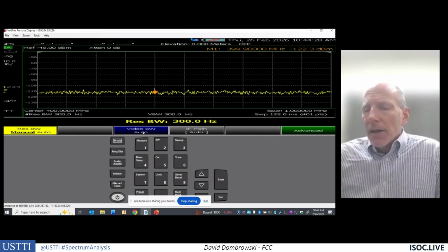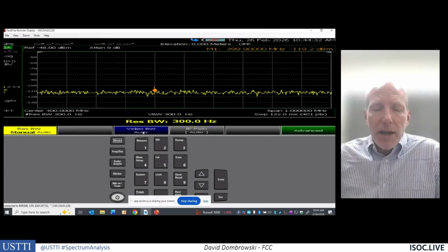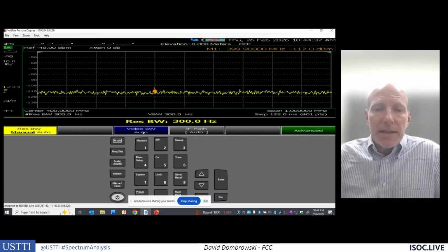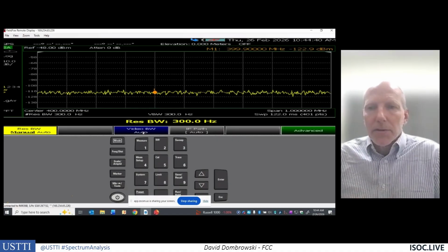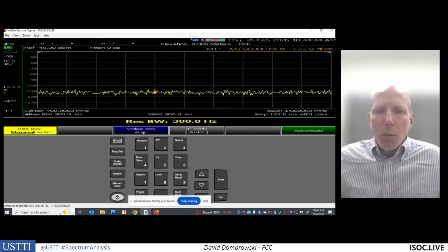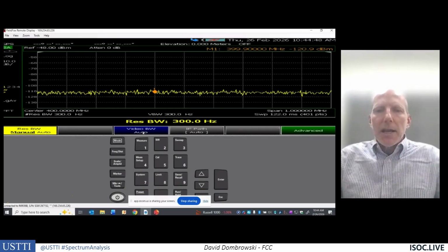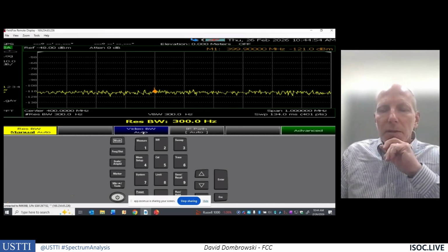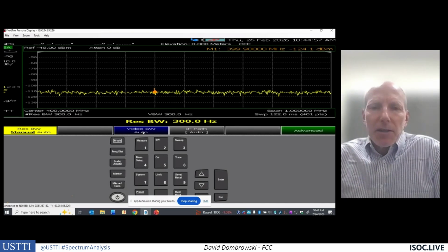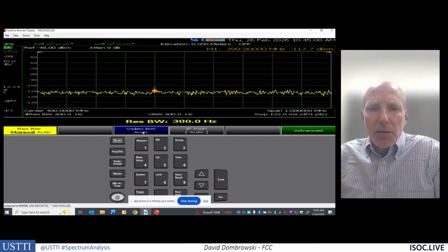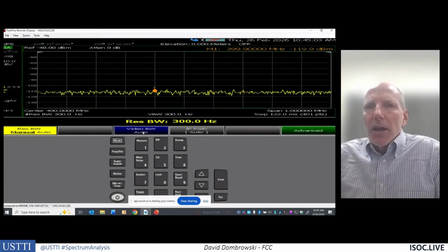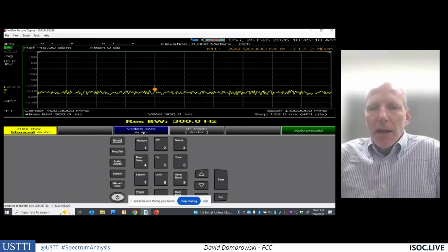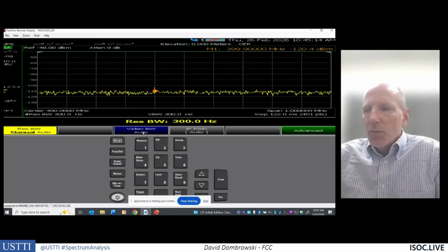So I start to lose reception or connection to my Wi-Fi router when I get about 100, 200 feet away from the source, and that's inside the house. So now we have the attenuation of the walls. But if that router was put out in the open, on nice flat terrain with no obstruction, you're going to get a little bit further than that, maybe 300 feet. But that's the expectation for routers. So you really have to be close to it. If you're direction finding Wi-Fi routers that are inside a residence, you pretty much have to be in the street out front to pick it up with the analyzer.